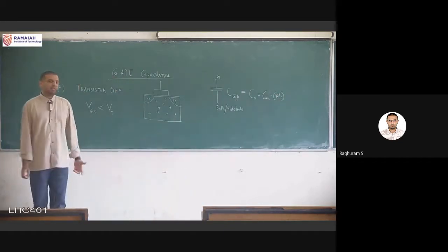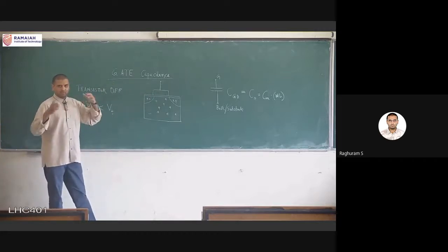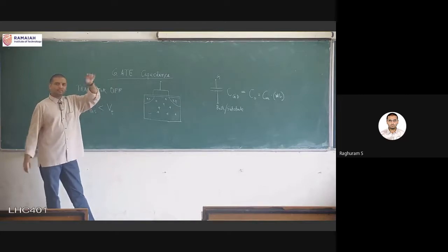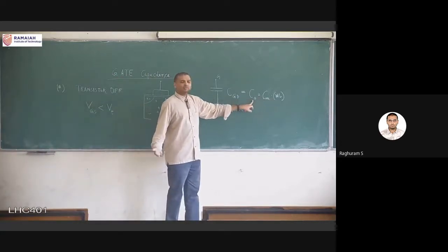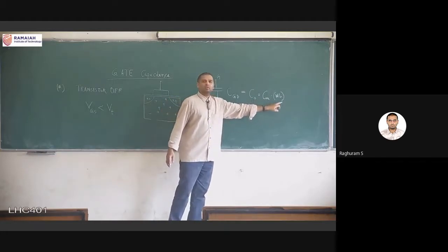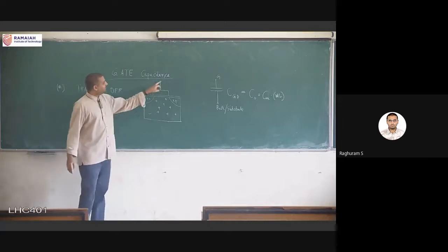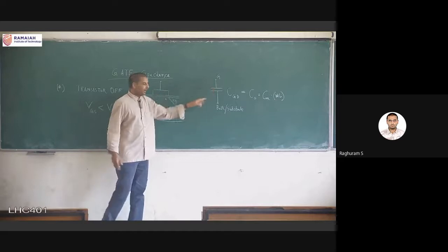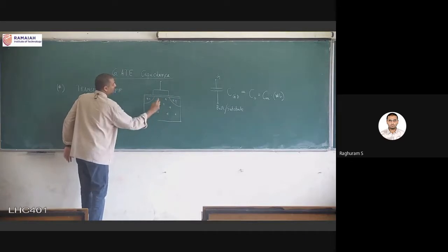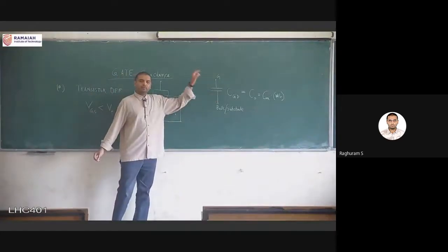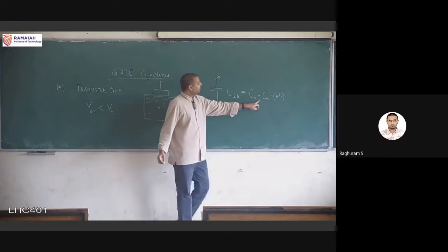The value of the gate capacitance itself is determined by the size of the transistor, that is the length and width. We saw the three-dimensional diagram. So the area of the parallel plate capacitor is W times L, and because of that, the total capacitance connected to the gate, which we also sometimes call C0, is Cox times W times L. So in the first region of operation, when there is no channel or inversion region being formed, one terminal of the parallel plate capacitor is the gate terminal itself. The other terminal is this full region, because this is all connected together. The full gate capacitance comes between the gate and the bulk terminal, that is CGB equal to C0 equal to Cox times WL.